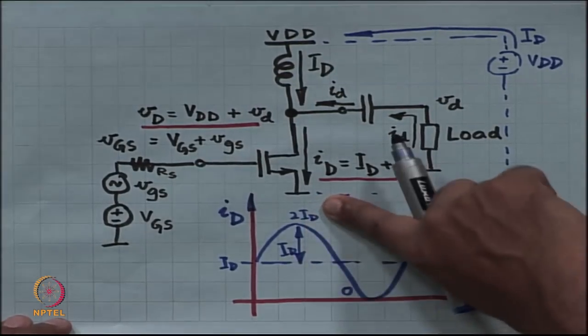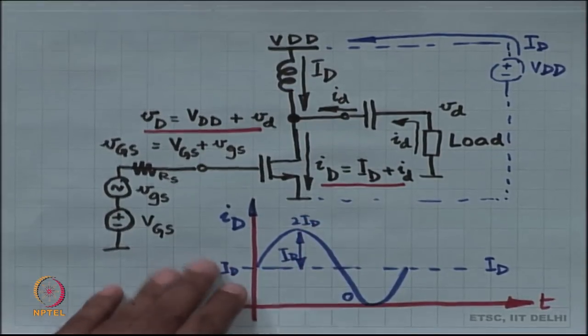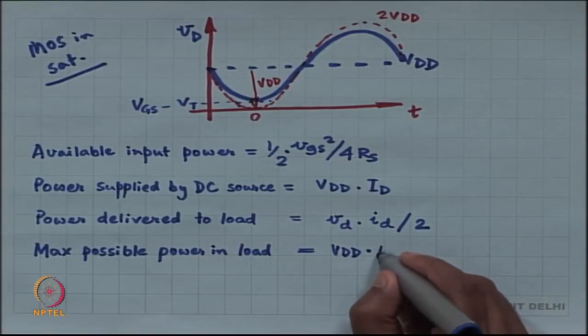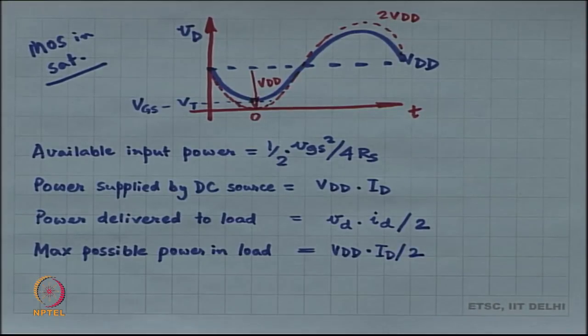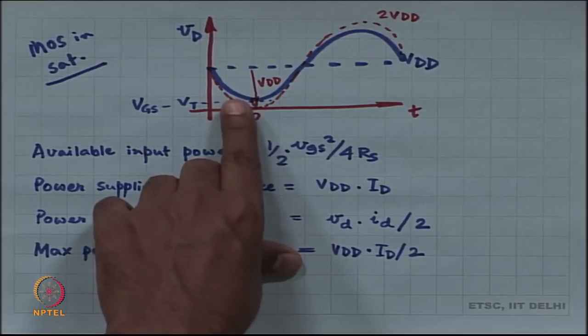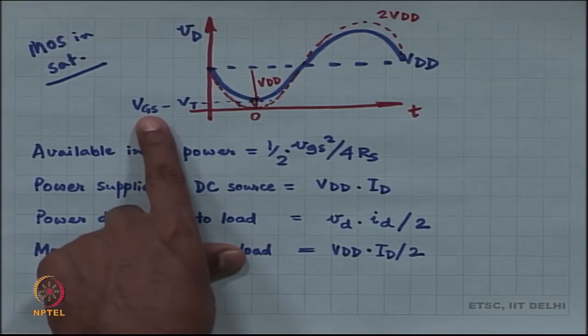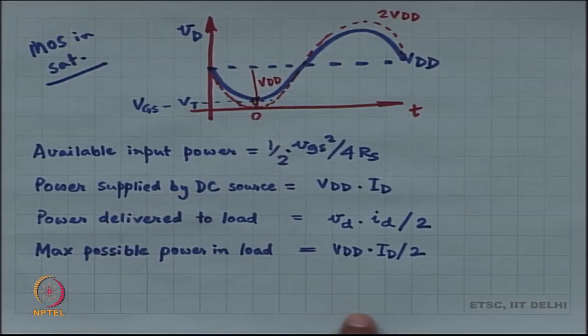Okay, 2 Id is where it is reaching the peak, the signal part, the amplitude is capital Id, and this is maximum possible. Vdd is not even correct, it is actually smaller than Vdd, right. The actual amplitude, if you take into account Vgs minus Vt, then it is smaller than Vdd, it is not even Vdd. Fine.